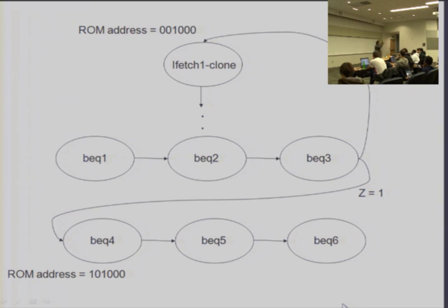Now there's a macro branch that is happening at your program level, which is a BEQ instruction, and there's a micro branch that is happening in your sequence, and we were able to effect that by taking the dynamic state of the Z-bit, right? The Z-bit has been computed in this state, and it contains the result of the arithmetic that you did in the BEQ instruction, and so you're using the result of that arithmetic in order to make the decision where to go. Is that clear?